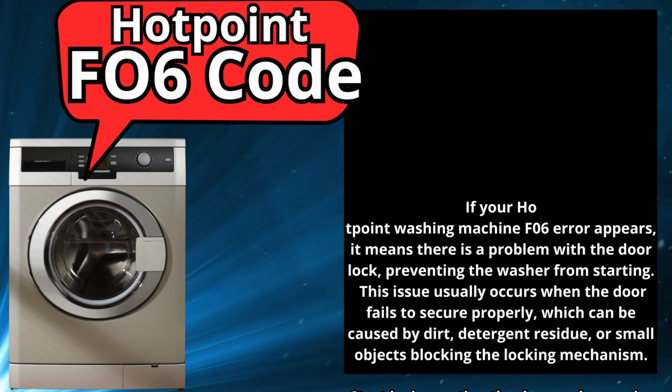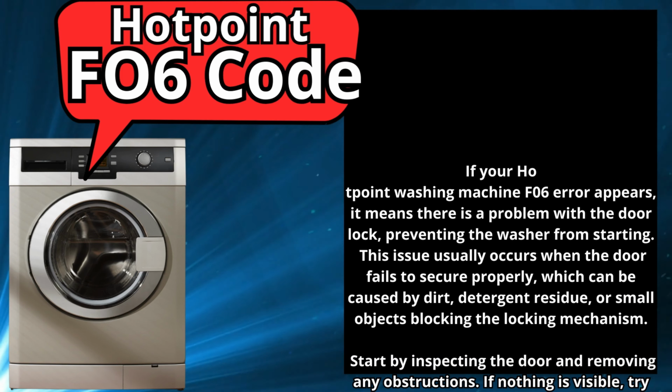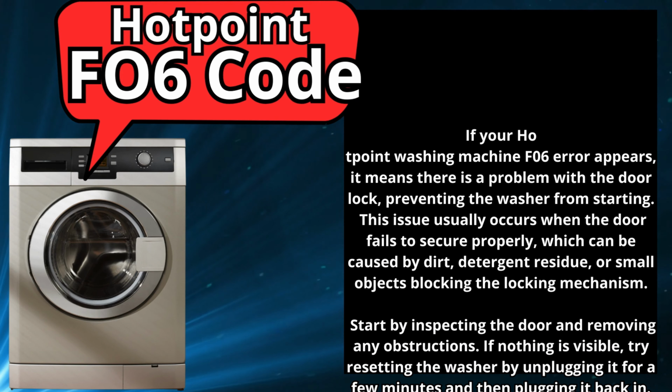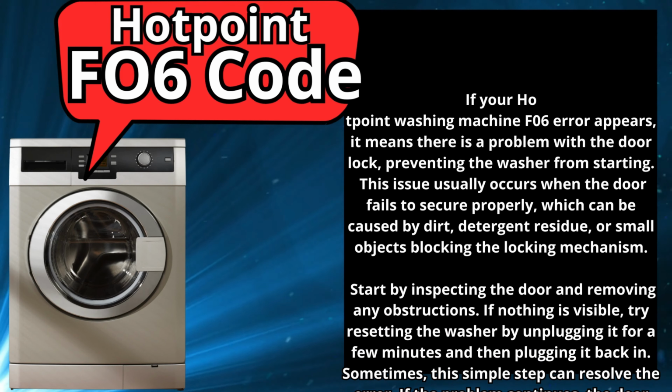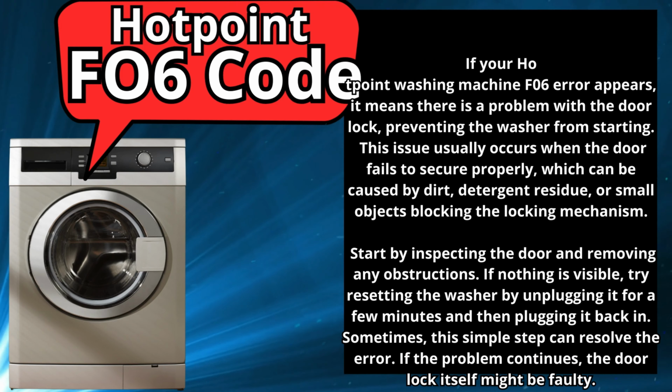If your Hotpoint washing machine F06 error appears, it means there is a problem with the door lock, preventing the washer from starting. This issue usually occurs when the door fails to secure properly, which can be caused by dirt, detergent residue, or small objects blocking the locking mechanism.